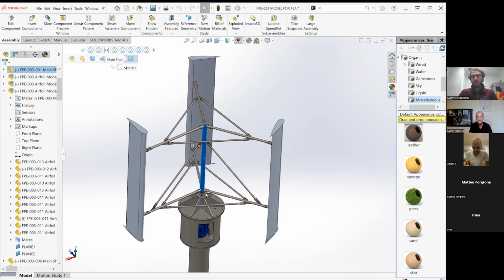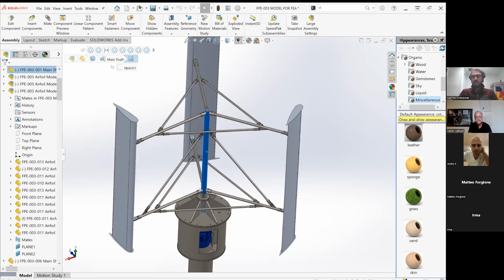In this case, we basically have to make sure that stress is below basically a reversible stress. Then we can analyze it and look at fatigue on that. Because this is obviously rotating around, you have some number of cycles where if it was above a certain level of stress, eventually it would just snap off. So you could literally calculate it out to exactly how many revolutions at a certain stress it would snap.